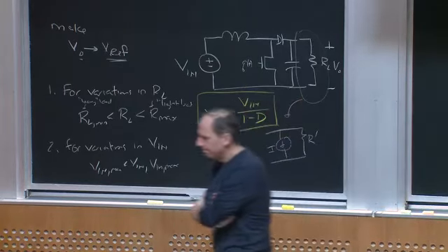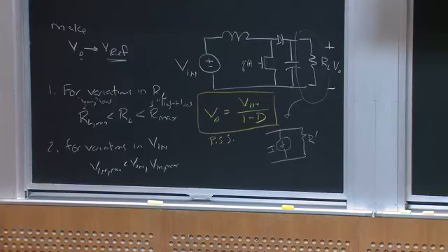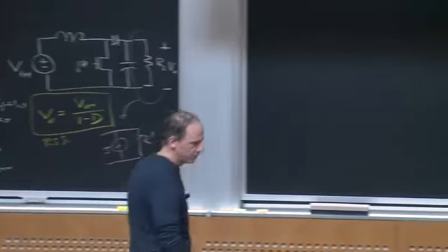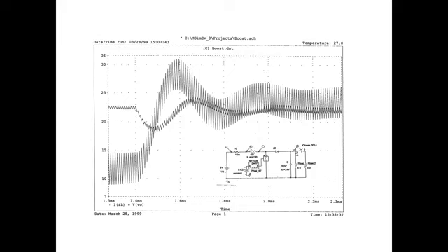Just to illustrate that, what I've got here is a SPICE simulation of a boost converter, which is undergoing a load transient, okay? What's happening is that at 1.4 milliseconds, we originally had a 5 ohm load on the converter, and we put in another 5 ohm load, right? So it's like some new load has come in. In this example, we're just holding the duty ratio of the converter constant, right? So we expect that barring a lot of second order effects, the output voltage should go back to the same thing in periodic steady state.